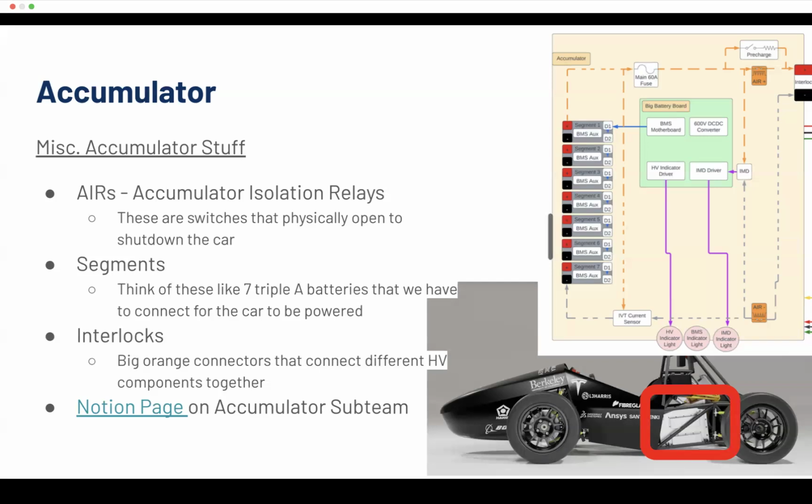We'll discharge that. So when I plug this in for the first time, you can imagine I have 0 volts over here, and I have 600 volts over here. If I just straight up went and connected that, I've just connected 600 volts through an empty capacitor, right? I discharged that capacitor, so it's empty. And when a capacitor is empty, it looks like a short. So I just shorted that 600 volts through milliohms of resistance, lots of current.